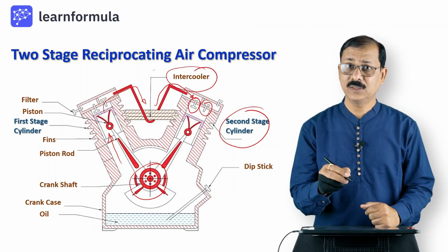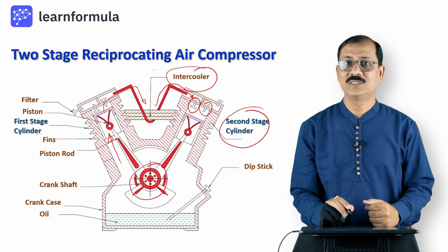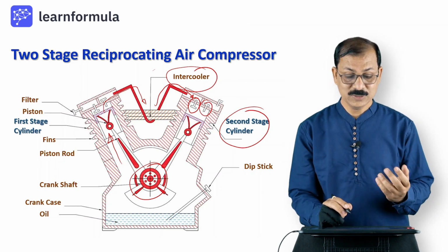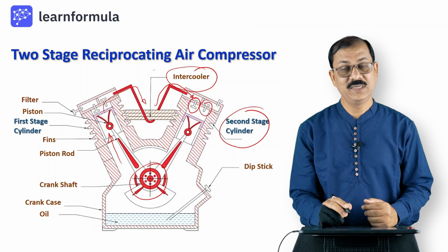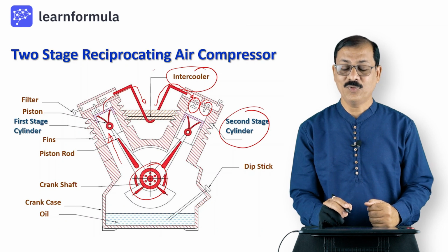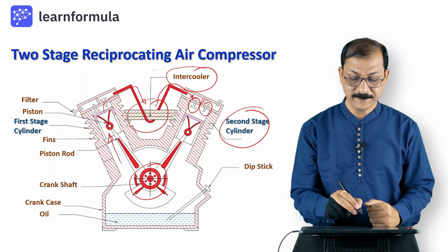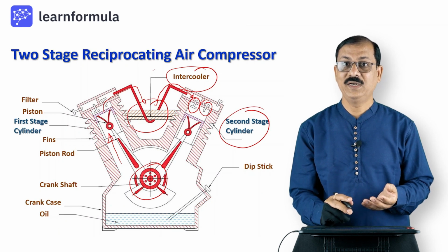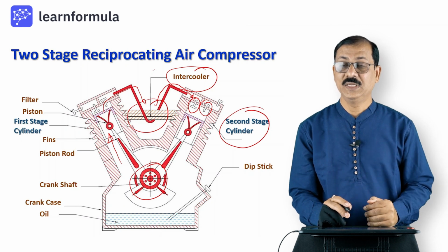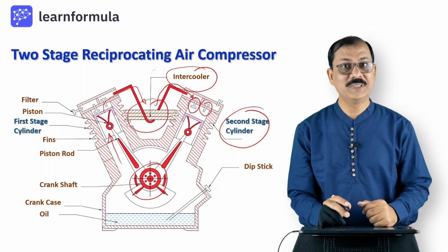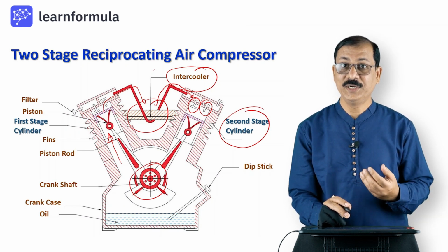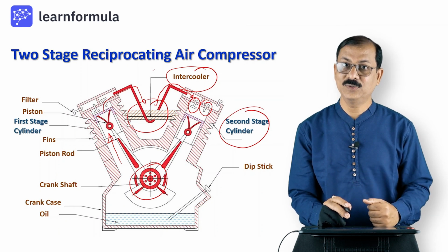What about this intercooler? As the name suggests, it works like a cooler, yes indeed, but it is working in between two stages. When the air is compressed in the first stage, the pressure increases, but at the same time the temperature also increases. We need to cool down the air, and for that purpose this intercooler is present. An intercooler is basically a heat exchanger that dissipates the heat to the surroundings and ensures that the temperature of the air drops. It also ensures that the overall performance of this compressor is enhanced because of losing that temperature into the surroundings. We need to improve the efficiency. For that purpose, this intercooler is present.